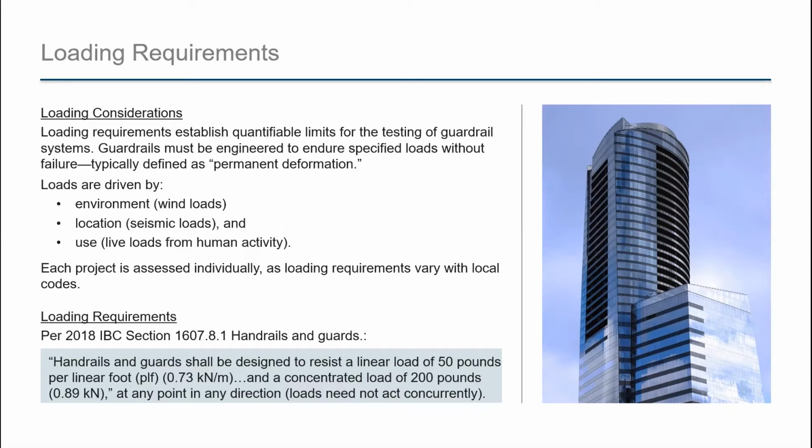Wind loads occur only on exterior railings and vary based on geographical locations. The eastern seaboard, for example, down through the Gulf, see much higher wind loads when compared to most interior regions. There are some mountainous regions that are exceptions, but there's frankly rarely structures in those regions. The wind loads are a function of the wind speeds, two different things. Gust speeds are what's provided in code in ASCE 7-16.